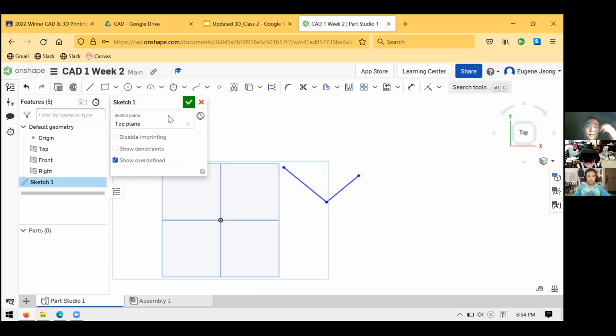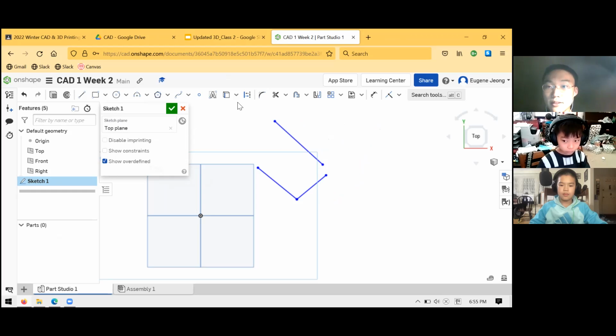So one more time from the beginning, this is called the line to sketch tool, and it allows you to draw lines in your sketch, in your 2D drawing that you're making right now. You select the tool by clicking on it in the toolbar once. When it's enabled, your cursor changes, and then you click once, you click twice, you draw the line, and when you're done, you can hit escape, or you can just click on the tool again to deselect it. So that's the basics. You just created your first sketch object, which was a couple of simple lines.